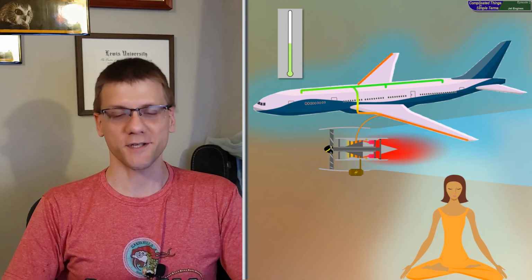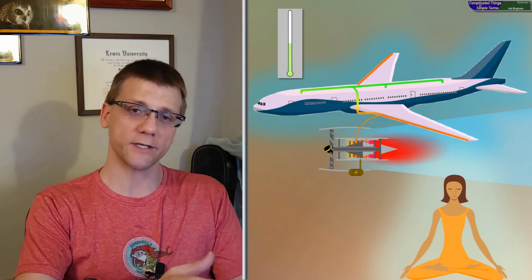That's how we get pressurized, warm air in the cabin, even though the pressure outside would kill you if the temperature didn't, at negative 50 or 60 degrees. Incidentally, when this air is being pumped into the cabin, it's sent up to the flight deck under slightly higher pressure than it is the rest of the cabin.